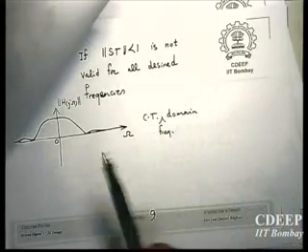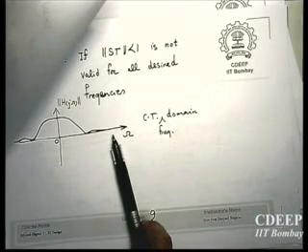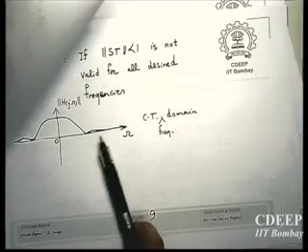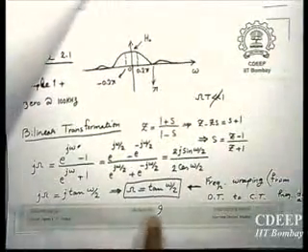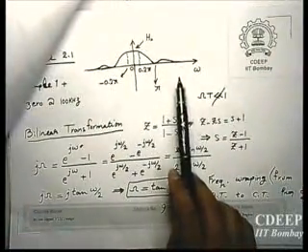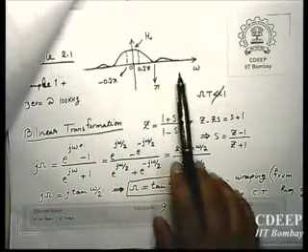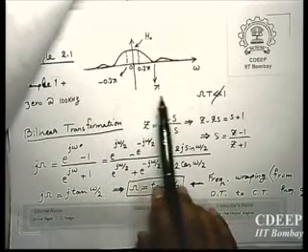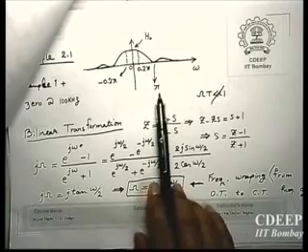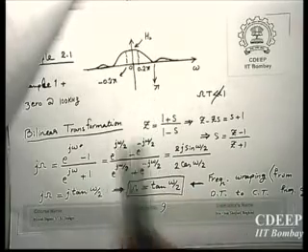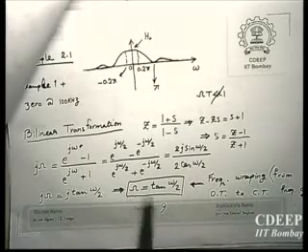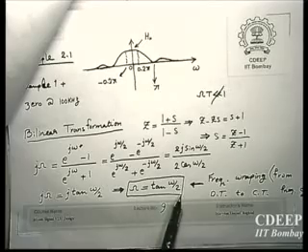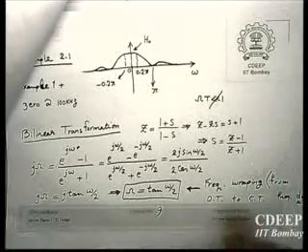The second part was to see what happens when we have a condition at which omega T is not much smaller than 1, like the conditions you have in a subband. This was the last point where we stopped yesterday. At the beginning I started writing the equations, like if I have a 0 at 100 kilohertz, which was exactly half of the sampling rate, then the corresponding omega in discrete time will be pi. Then I explained, if we don't have this condition, what will be the relation between capital omega and small omega? This relation was derived, and it is called frequency warping.